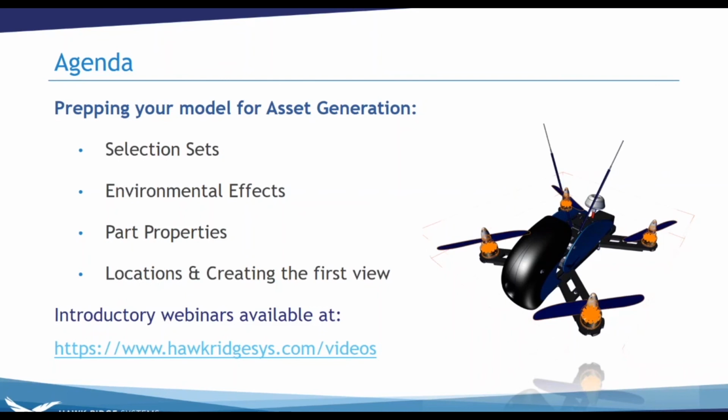And then afterwards, the part properties, where we can change one component individually, and then if we like the appearance, we can copy the appearance over to any of our other ones so it can populate. We also modified opacity properties, where, say, with transparency, we want to be able to see inside some of our components. The opacity slider allows us to make our components a little more transparent. Then hiding components and changing the render style.